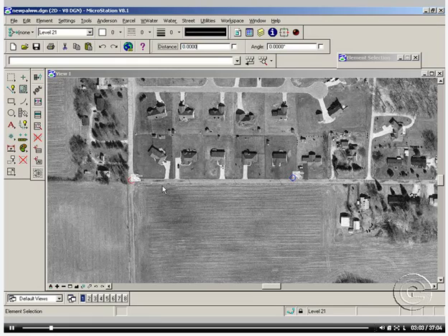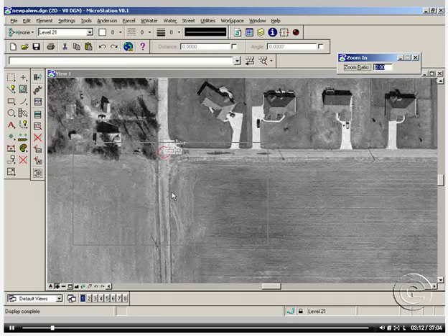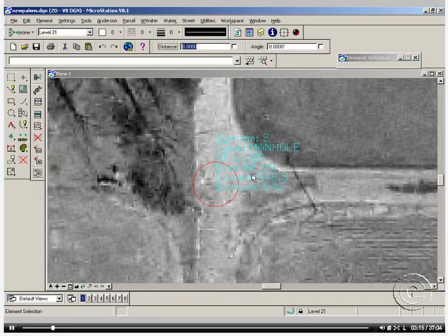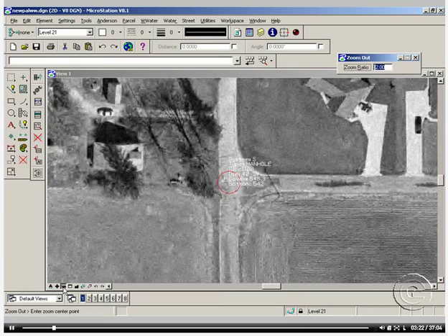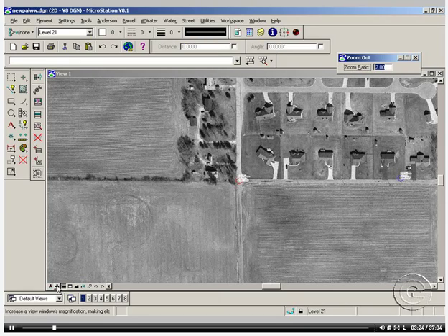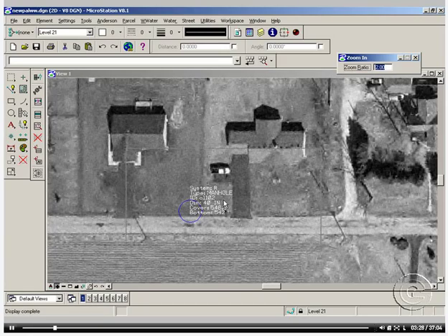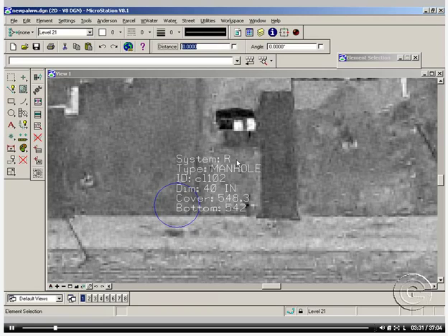As you can see here, you have 2 different circles. One is red and the other one is blue. The red represents the wastewater system, and the blue represents the storm or rain water system. And as you zoom in on those nodes, you would see that each node is annotated with the information that you typed in those forms, which also goes into the database for that specific node. We can zoom out and zoom into the other one also, so you can see exactly the different system. In one, the system was S corresponding to wastewater or sewer, and in this one, the system is called R corresponding to rain or storm.